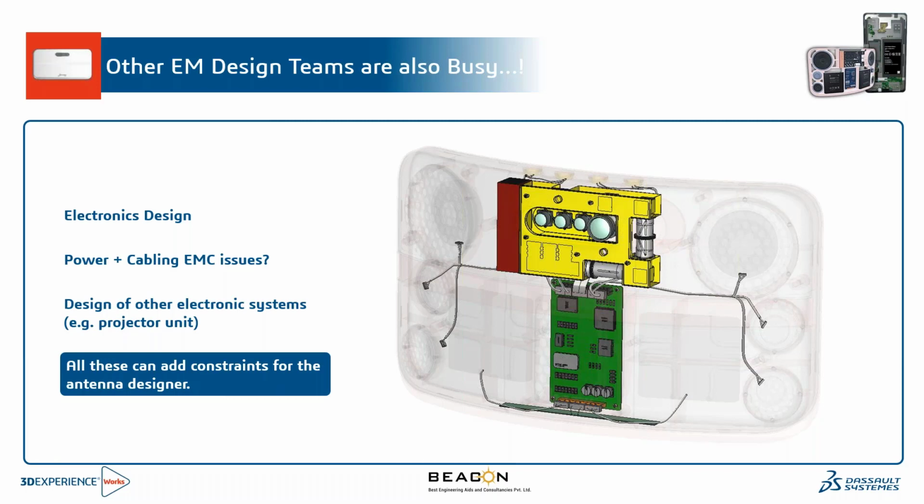Based on your internal teams' discussion, you can look at which positions are possible. Then you can try various permutations and combinations by positioning a similar type of antenna, or, if your design requires two different types of antennas operating at different frequencies, you can place them at the required positions and cross-check the coverage. You will get to see the coverage efficiency, and based on that, you can decide which is the best suitable position.